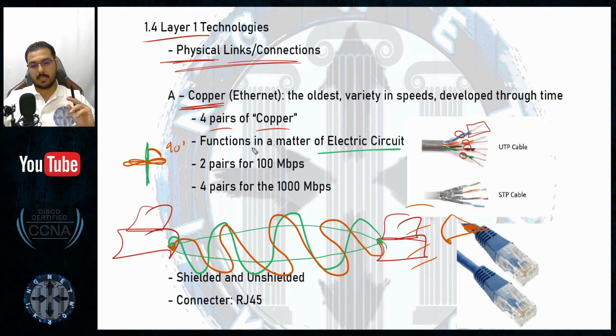Each one of the magnetic field will not interrupt, but will, what do we call it, will implement some noise. Yeah, it will interrupt and apply some noise to the electric field in that case, because it's touching it every time, and that will definitely affect the transmission that you want to do. The solution will be to twist the pair of the copper wires.